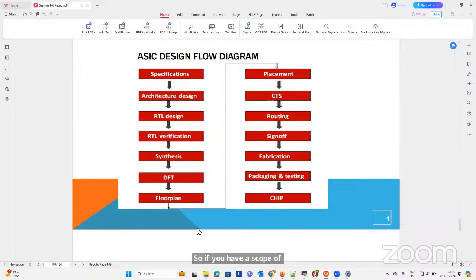Next, once the RTL verification is passed, the RTL team will give the final Verilog code to the synthesis team. The synthesis team will understand the code and ask for the design constraints. If they don't have design constraints, they will sit with the manager and write them. They load all the libraries, such as technology library, timing library, area library, and power library, into the synthesis. The process of synthesis is converting your RTL to a gate level netlist.